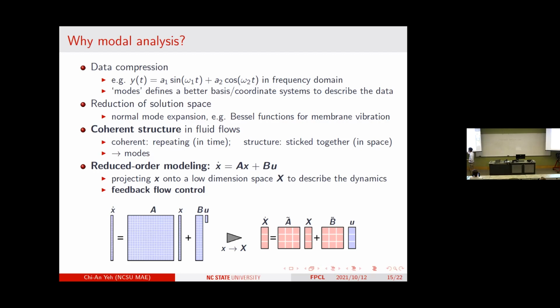But if we end up having a million by million dynamical system of the fluid flow motion, while mapping it to this basis or to this coordinate defined for these coherent structures, we may just need to describe the dynamical system with only three factors. That's a huge amount of reduction in space. Now you can implement that for, say, your feedback control law to do real-time control. That's how flow control technology, if you want to advance that, this is a major challenge we want to address.